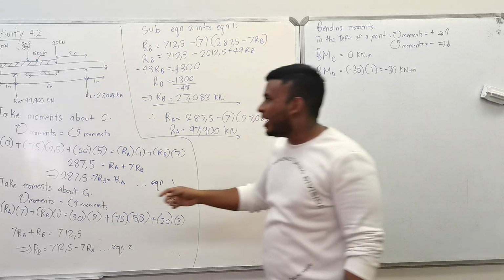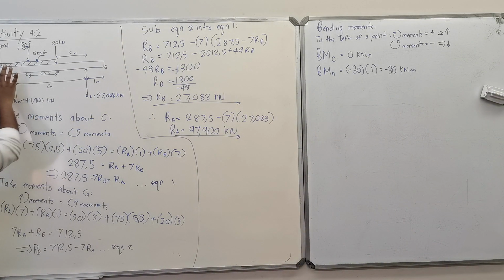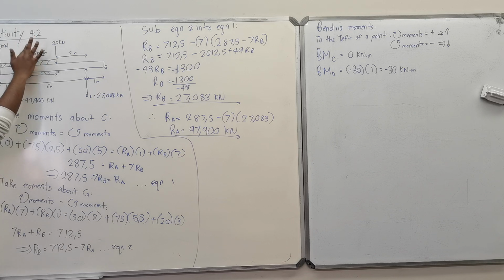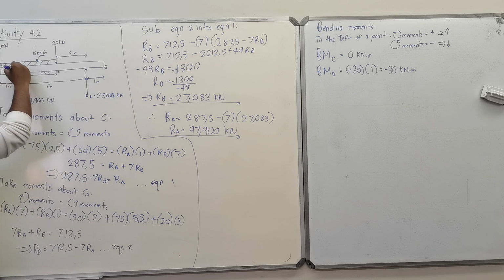Yeah. We left out that, see when you're looking at this beam, right? Remember, this uniformly distributed load, if we're looking at point D, it also has a small portion of uniformly distributed load. Yes? And that will also apply a downwards force. So you can't just disregard it.